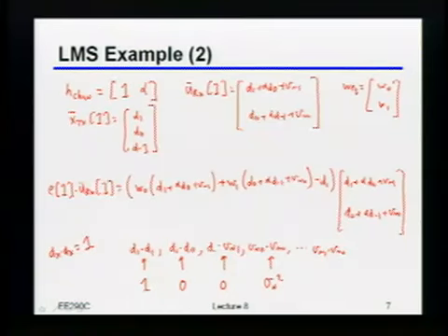So the reason I wanted to point this out in this level of gory detail is that this is now really giving you a hint as to why this is converging to the MMSE solution, right? Because all the terms that are uncorrelated with each other just fall out. And only things that are related to correlated errors actually come into this equation. In particular, it's important to notice that the noise sticks around because you get things like the variance of the noise popping up in your average error term, okay?